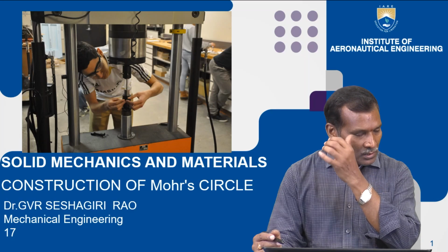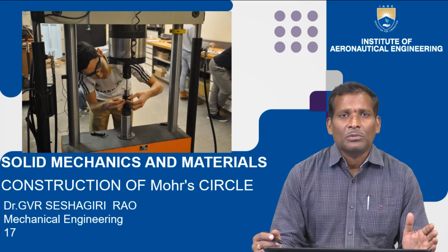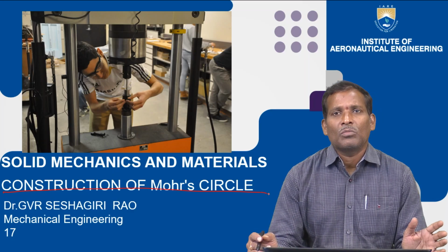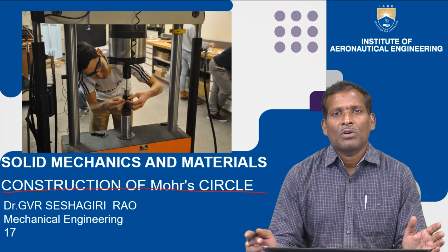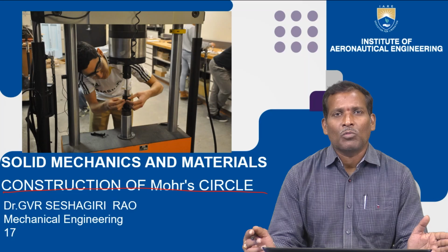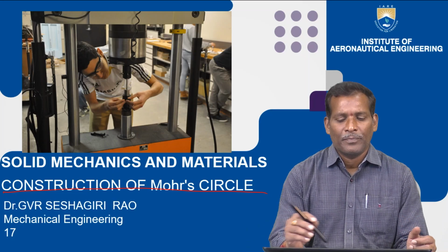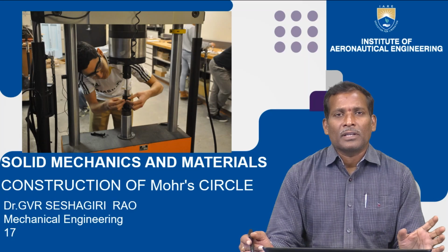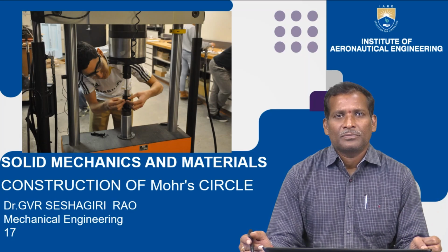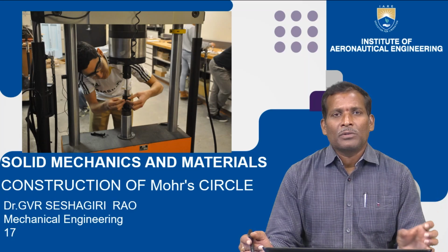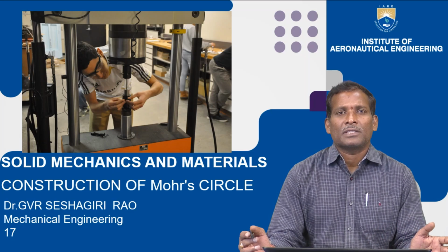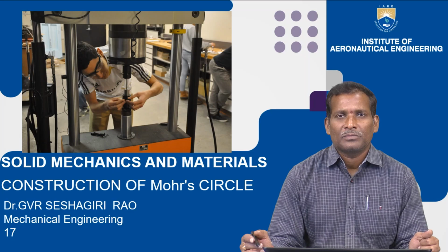So in this session, I want to explain the construction details of the Mohr circle. How to construct the Mohr circle? What is this Mohr circle? This is a graphical representation for principal stresses. By using this diagram, you can find the maximum principal stress and minimum principal stress.